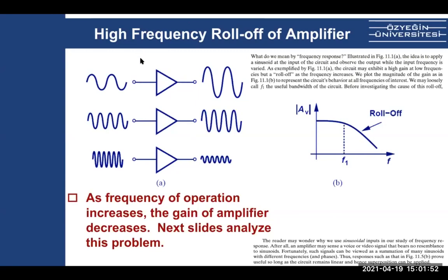What we do is apply a sinusoid signal into the input. You can do that in PSpice, like 5 sin omega t, or you can make the amplitude variable and apply it to the input and change the voltage. That shows the linearity of this amplifier. Linearity means how your circuit responds with increasing voltage. Eventually you won't be getting the same gain.